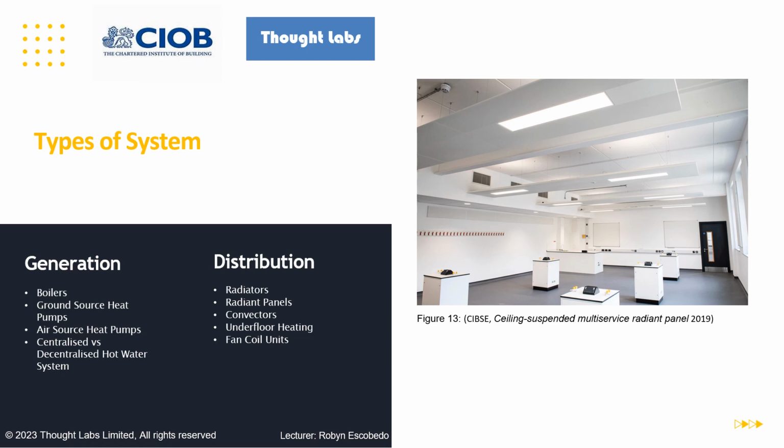There are diverse applications for radiant panels, with them being able to be suspended directly from ceilings, installed within walls or ceilings, or installed within suspended ceilings as little ceiling tiles. An advantage of radiant panels would therefore be that space isn't taken up, they can fit in with aesthetics, and there'll be none of the implications on escape distances like there is for radiators. Similarly, there'll be no implications on furniture layouts.